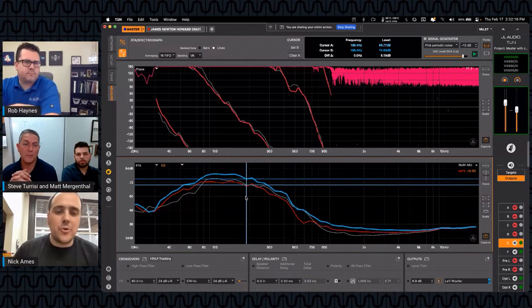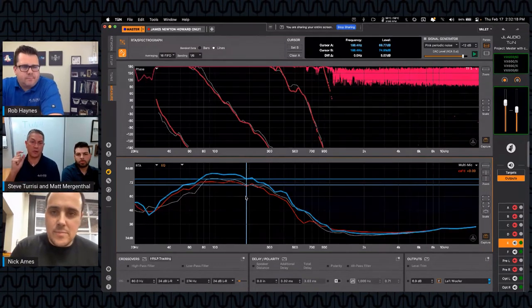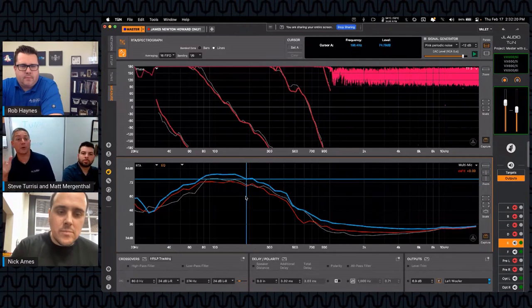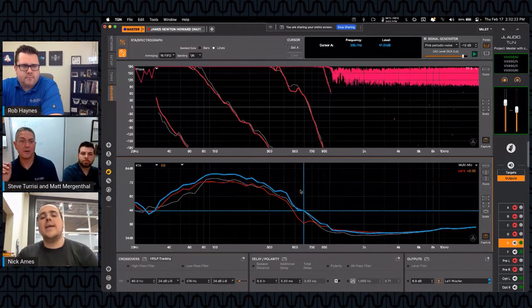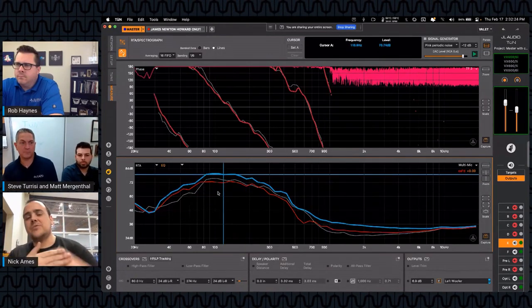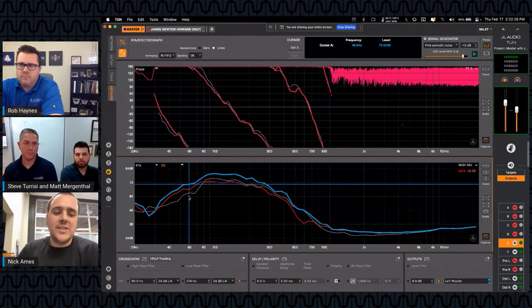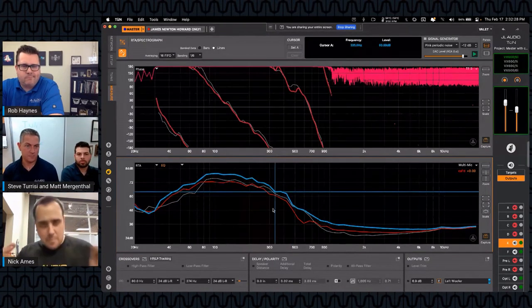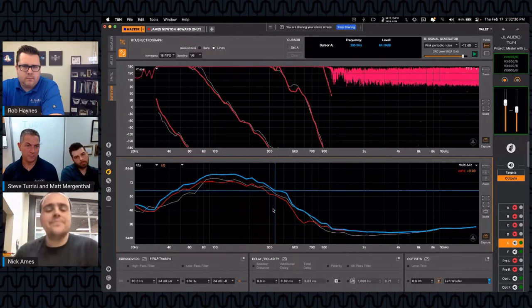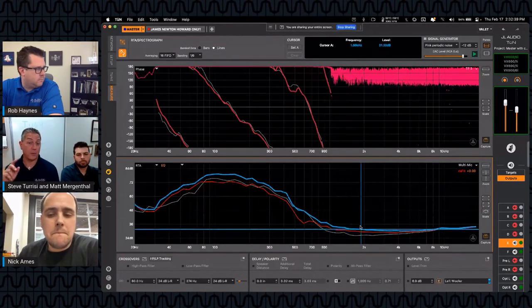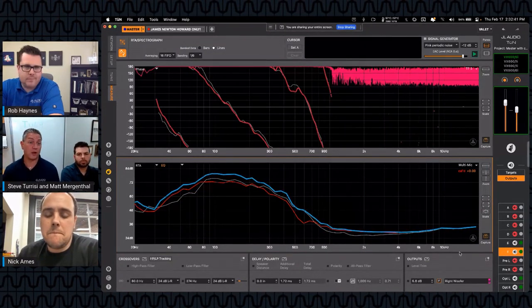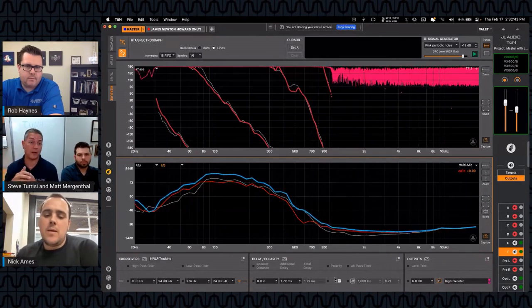So in summation is 5.1 dB, just a slight difference off of an ideal perfect electrical summation. Yeah, so it's somewhere around 6 dB, right? That's what you ought to see, about a 6 dB increase in level if the two contributors are identical. If you flip the polarity on one of the mid-bass drivers now, we can see what would change with the summation of one that's out of polarity with the other.